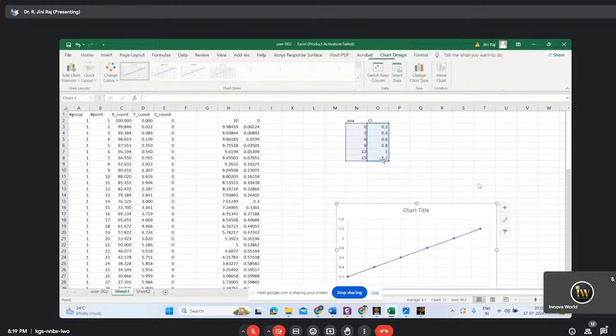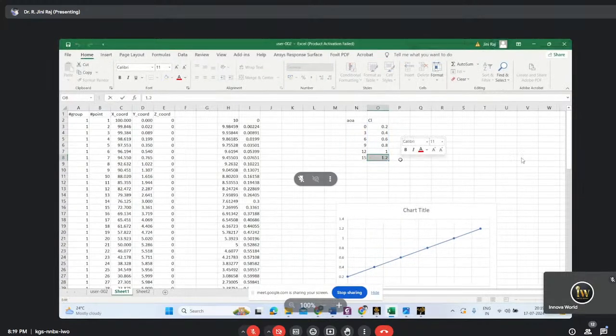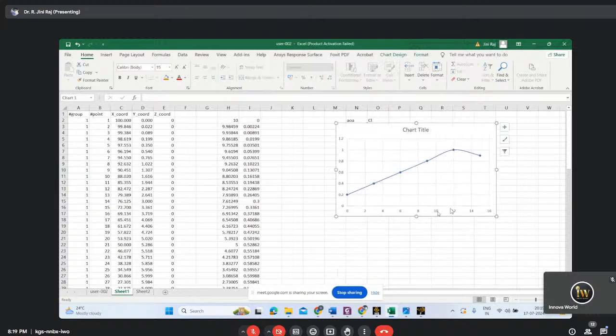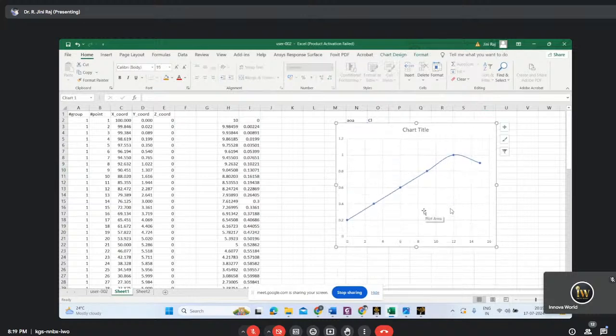If here it is getting stalled, see, you will get the CL value. This is the CL curve. Like this only you have to plot. No other way. In Ansys, you will get values only for one angle of attack. If you are doing n number of analyses with different angles of attack, you can easily get the values.